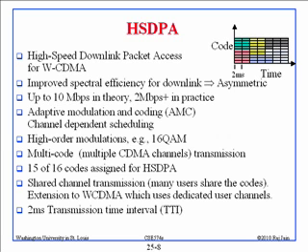Multi-mode. Now this is the thing which needs to be explained. Multi-mode, multiple CDMA channel transmission. So what is a CDMA channel? The way that we do CDMA is that we develop codes, and you get a code, you get a code, maybe a 16-chip code, that is called 16 chips per bit, right? So if we get a 4-bit code, we get 16 codes, right? Anyway, we get those codes, and then we give one code per user. So then one user can use only one code, only get one channel worth of bandwidth, and only one channel worth of data, and that may not be good.